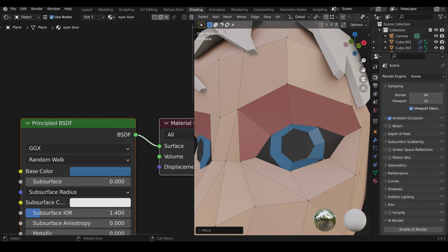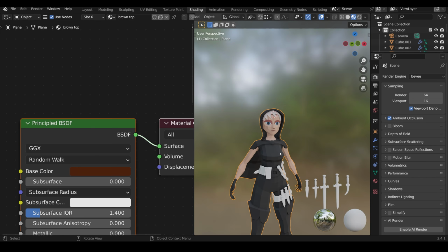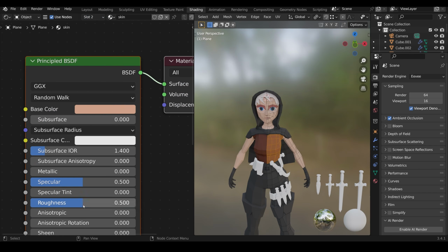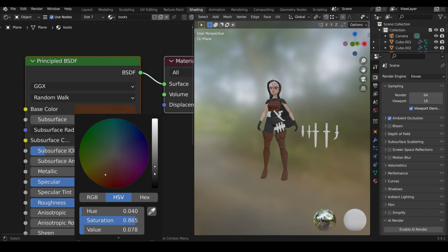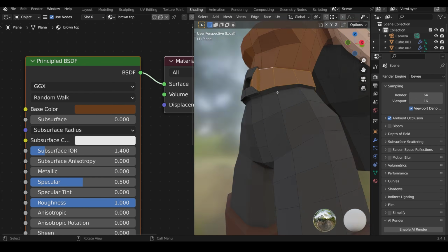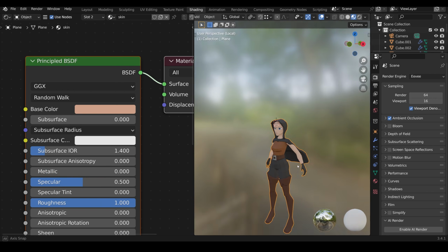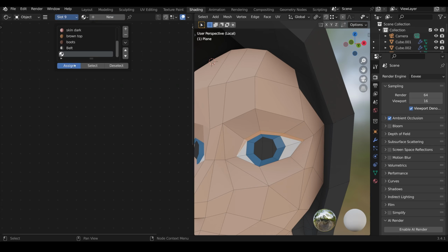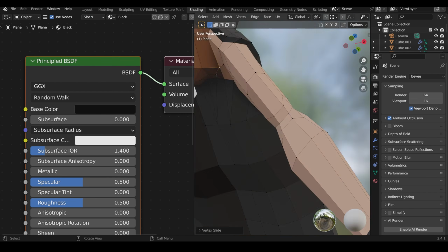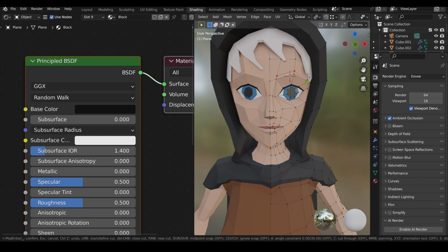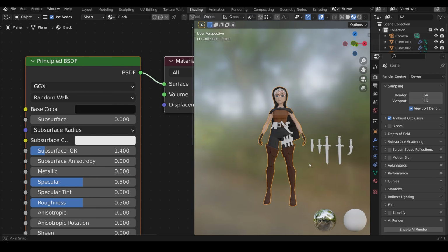Also, you'll notice that I do create more topology now because I need to cut the mesh up so that I can assign the faces to the right colors. I don't worry too much about whether this is a quad-based mesh at this point because I'm not doing any more extra modeling. And that is the major reason why you want to keep your modeling to quad-based meshes, because it's much easier to model because you can loop cut through them and so forth. As soon as you put in an n-gon or a triangle, you lose that ability to do those loop cuts. And as you may notice, for low poly characters, I'm generally not doing that many loop cuts, to be honest. So it doesn't affect me too much. What I'm basically saying is, don't panic about using n-gons.